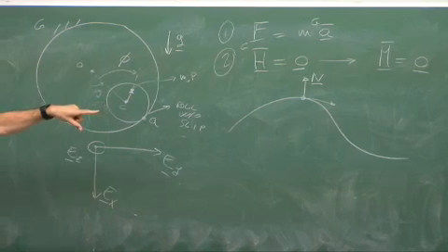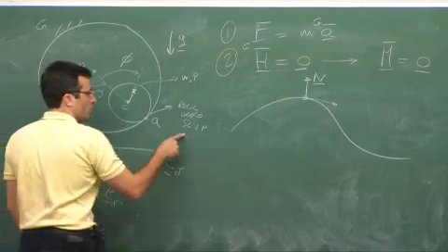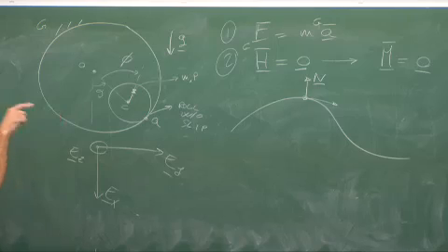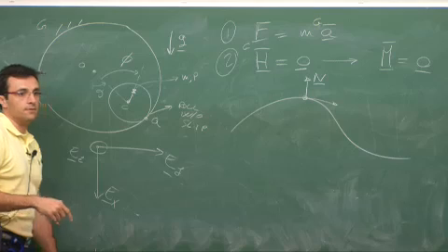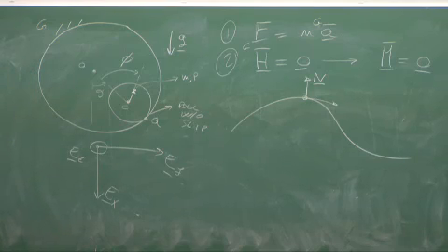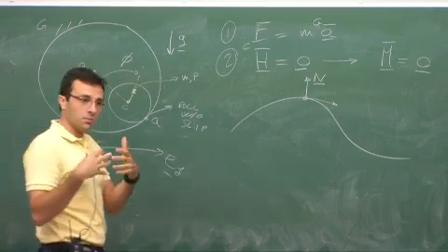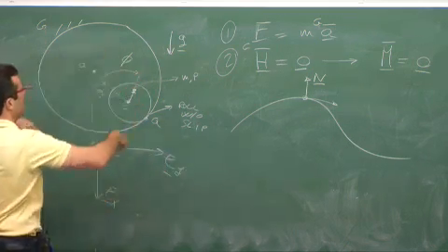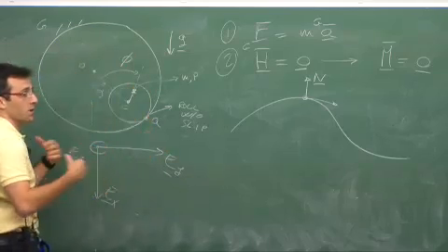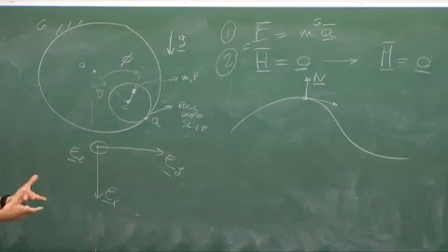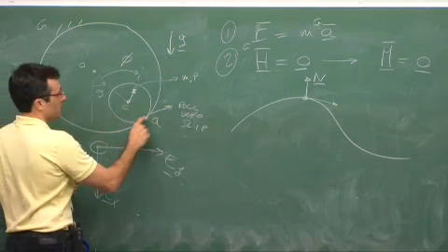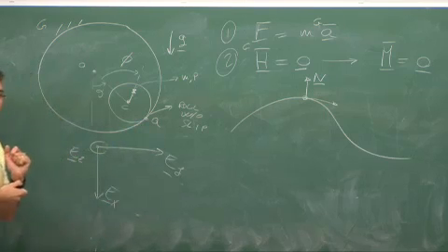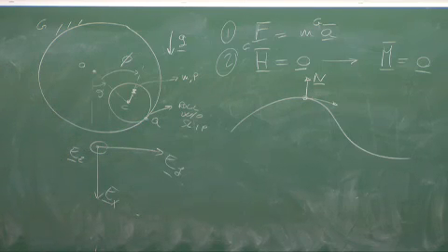You will still need a static friction force between the two so that you can have roll without slip. So that friction force actually is a constraint force, and it does not make any virtual work because this point has no velocity. When you freeze in time, you're constrained. Does it make sense? Can you relate back to that concept of freezing the constraint? This circular guide outside can move around. I don't care. When you define virtual work and virtual displacements, you freeze it. So here it is, frozen. When I freeze it, these two forces don't make any virtual work. So they don't need to go into the Lagrange equations.